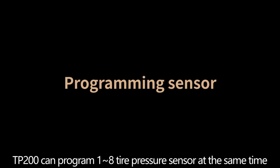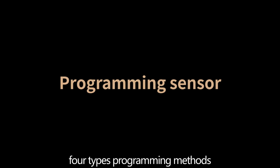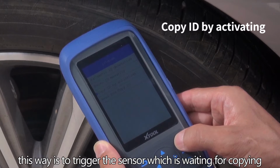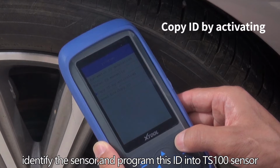TP200 can program 1 to 8 tire pressure sensors at the same time. There are 4 programming methods. First, Copy ID by activation. This way is to trigger the sensor which is waiting for copying, identify the sensor and program this ID into the TS100 sensor.